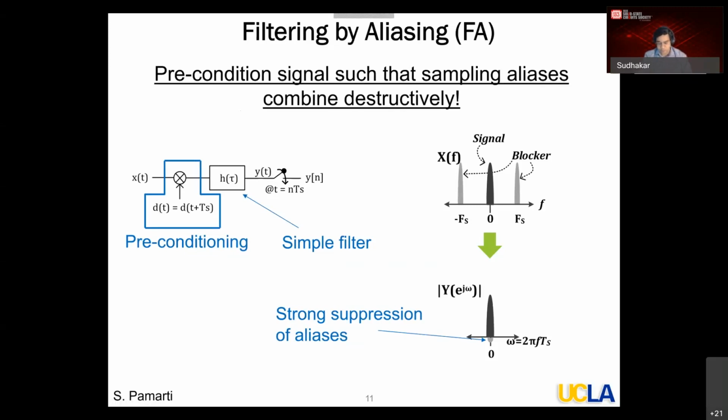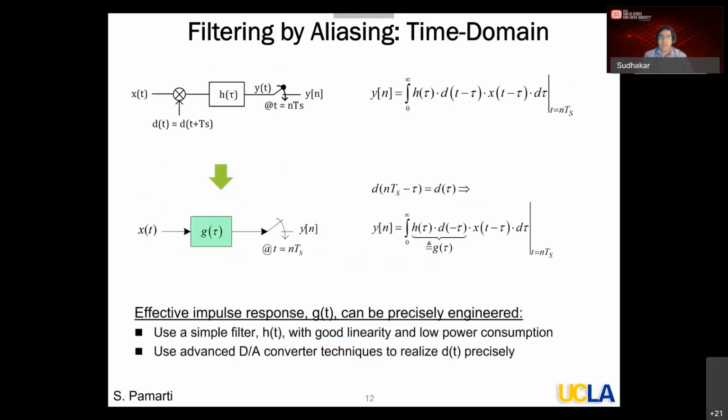So first of all, the first big hurdle in dealing with a system like this is that it's time variant. So our general analysis methods, which are based on Laplace transforms and Fourier transforms, don't really work very well here. But fortunately, because it is time varying, it turns out it's actually fairly easy to understand what's going on. Now, since I'm eventually going to sample the signal at Ts, let us consider the samples.